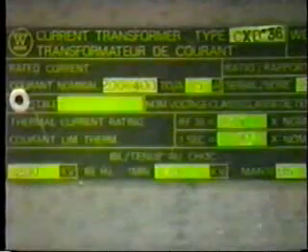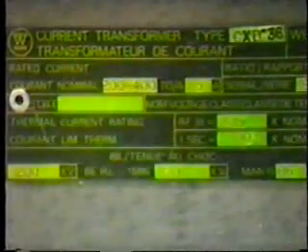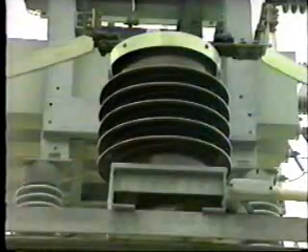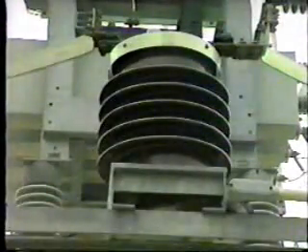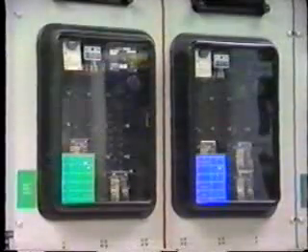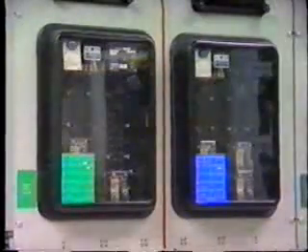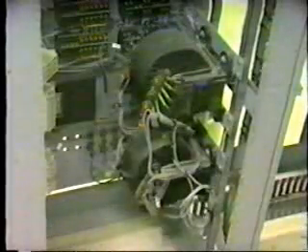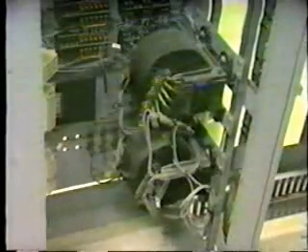In order to improve accuracy, it is important that the burden on CTs be kept as low as possible. Therefore, the CTs should not be used for any other purpose. For the same reason, the leads connecting the CTs should be of ample current carrying capacity. As all of the CT ratios are normally identical, the bus differential relays are not fitted with ratio taps. If a particular circuit does have a different CT ratio, then it's necessary to connect an auxiliary CT in order to match the others. Okay, so much for current differential.